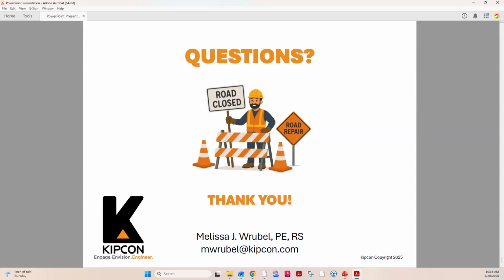I'm not sure what you mean by ultra thin lift HMA, but I know there is what they call a slurry coat. If your roads are older but in relatively good shape, they can apply that and it'll kind of buy you another few years. It's not really a full depth asphalt course or anything like that, but it does have some protective qualities for older pavements.